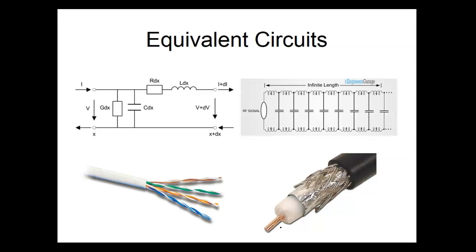So when we moved over to cable, we didn't have a cable input on our TV. All we had was the 300 ohm input. So you bought what we call an impedance matching transformer. On one side it had an impedance of 75 ohms, on the other side 300 ohms. So that's another thing we can do with transformers: we can literally match impedances. 300 ohms and 75 ohms is very, very popular.